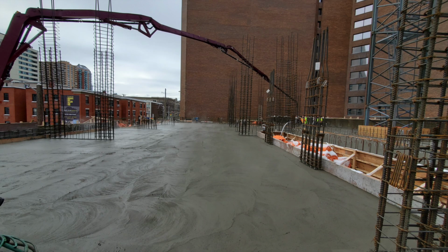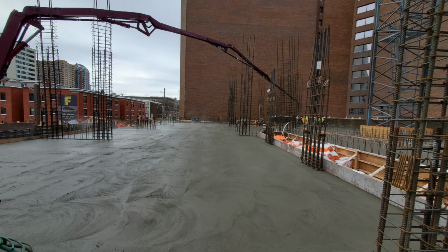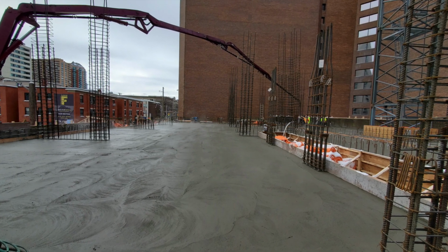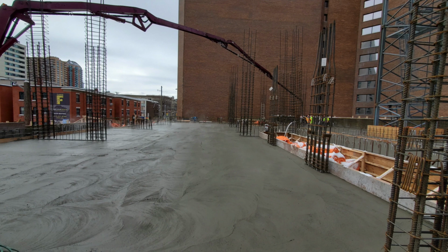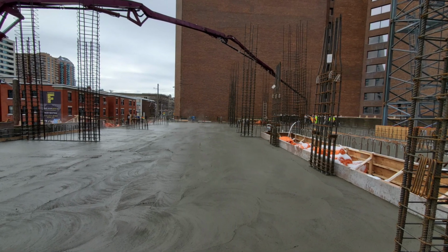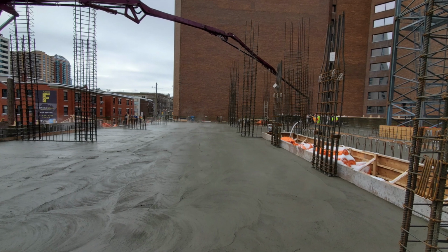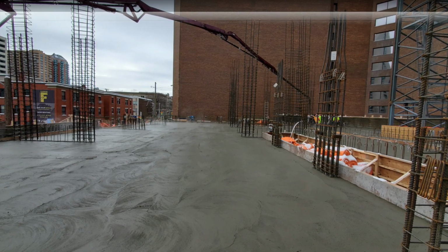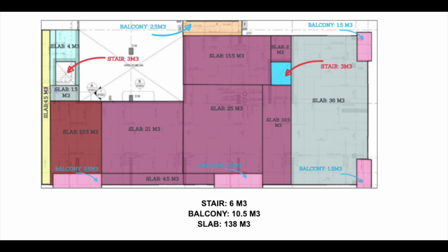On my project site, to help ensure that we're able to pour 45 cubic meters per hour, we are using a concrete boom truck to assist in placing the concrete. So once the pour break has been defined, I will do an initial rough estimate using PLANSWIFT.